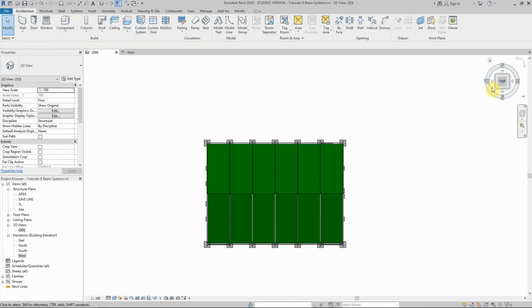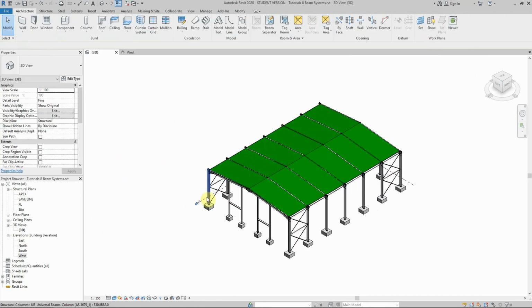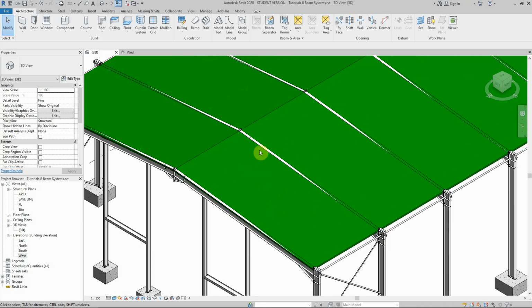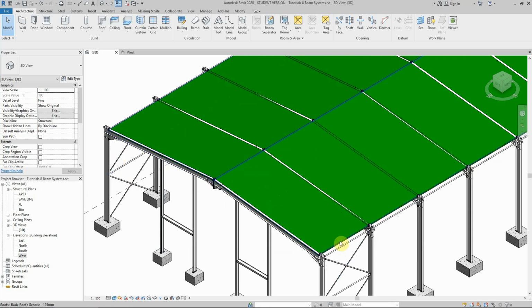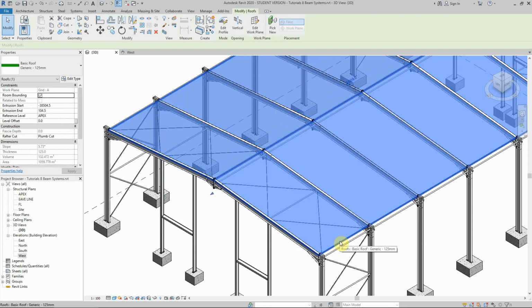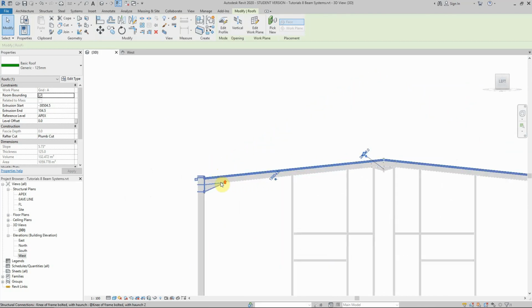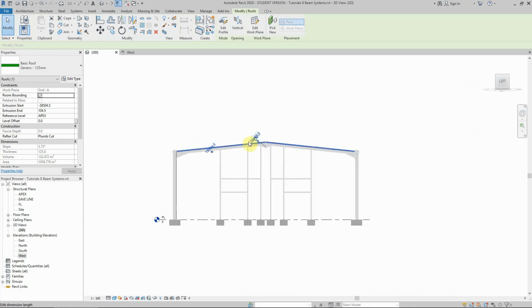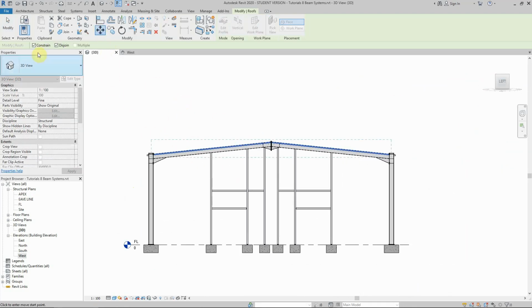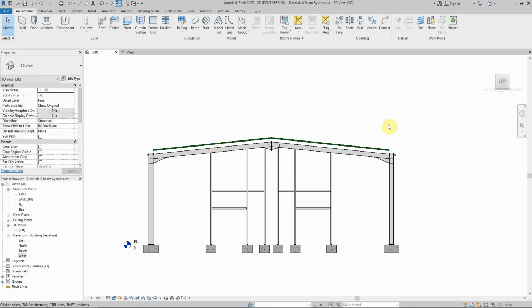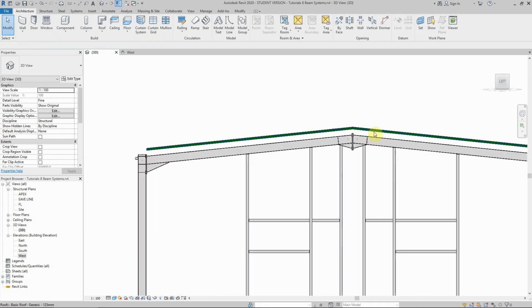It's good. Now looking at the roof from here, because we've got the roof now sitting within the framing members and within the rafters and all of those, it's just easier, and you'll see down the track why, if we can keep those separated. So if I move the roof upward by say 500 millimeters, so if I look at it just from the edge here and move the roof, keep the constraint on and move 500 millimeters up. That way I'll separate the roof from everything underneath, because as we said, we want this roof just as a plane for us, as a guidance, that's all.